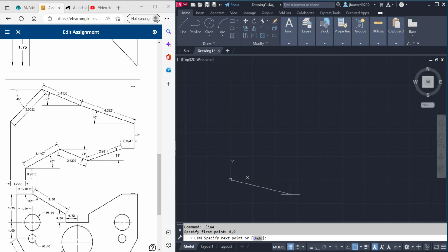All right. So when you're looking at that, you can actually do two things. And this is one of them, and we're going to see this a little bit more in another little lesson. If I wanted to make this a 30-degree angle from 0, so come off 0 up 30 degrees, and I want it to go, let's say 10 inches, I can type in 10, it's the length that I wanted, and I put that sign in right there, okay?